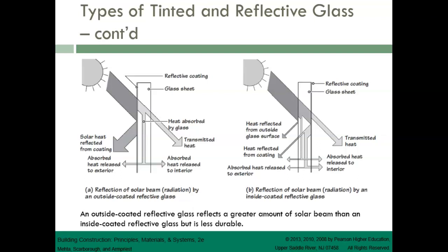If everything else is the same, a green tinted glass has a higher LSG index than any other tinted glass. Reflective glass works as a mirror from the outside during the day, hiding interior activity. At night, however, the interior activity is visible from the outside when the interior space is lit.